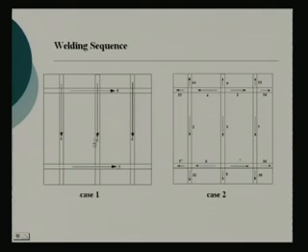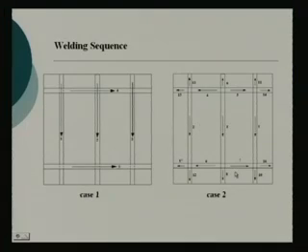You see, in case 1, when I have done all the 5 sequences, I have completed the welding. They are straight cases of 5 runs. Well, in case 2, when I have done 5 weldings, it was the middle part of the central longitudinal, then the outside longitudinals, both, and a part of your transverse.